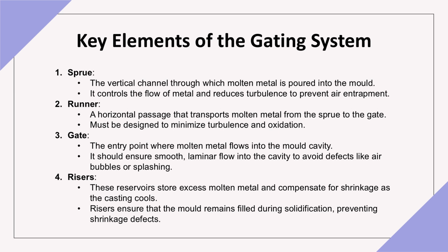Gate, the entry point into the mold cavity, allowing molten metal to flow smoothly into the cavity. Risers, reservoirs that store excess molten metal to compensate for shrinkage during solidification, ensuring that the mold remains filled.